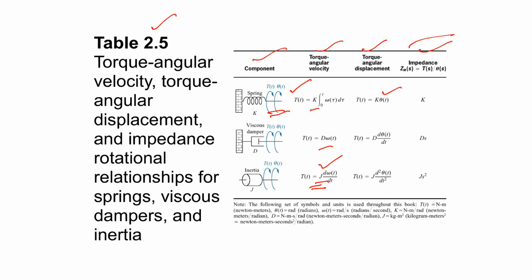Now writing the equations for more than 1 degree of freedom of this rotational system is similar to writing them for a translational system. The only difference is that the free body diagram consists of torques rather than forces. We obtain these torques using superposition. As in the previous case, we rotate the body while holding all other points still and place on the free body diagram all torques due to the body's own motion.